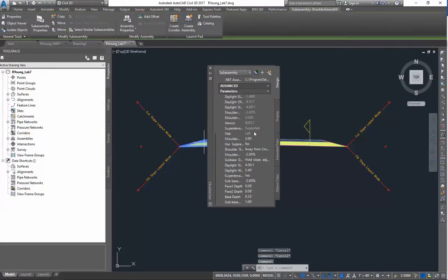So we set it to right outside, and we had this at yes, and then down here I think we only changed it in one place. We want it to use it. This is going to be the left outside shoulder. Because we don't have medians, we don't have inside, like if this was just part of a road and then there was a median, we could have it being inside versus outside. Everything we're going to have is going to be the outside, and it's either going to be left if we're on the left of center line or right if we're on the right of center line.